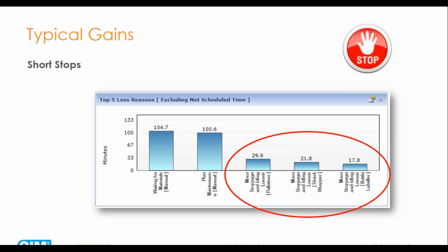One of our clients recently said that they were stood on the shop floor with their back to the line. They hadn't even noticed that the line had stopped for around 20 seconds before they turned around and saw that it had stopped. And as you can imagine, we're only human. It's very easy to miss that kind of information, but it's also very important that we have exposure to that information because it could be one of our top losses. So short stops of less than 5 minutes are a key or an easy win that you can achieve by measuring OEE in real time accurately.